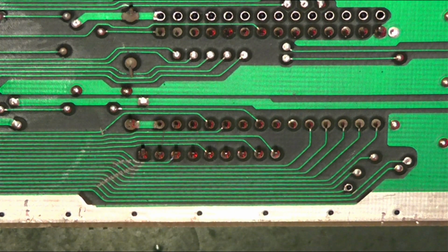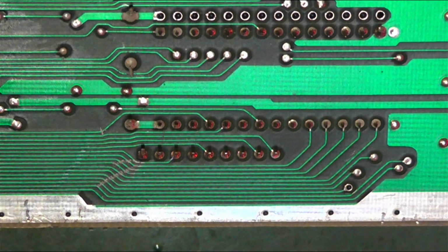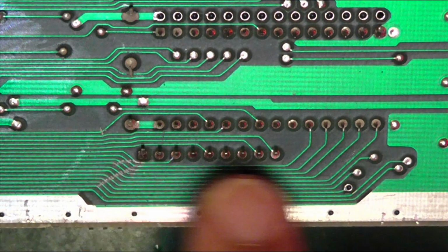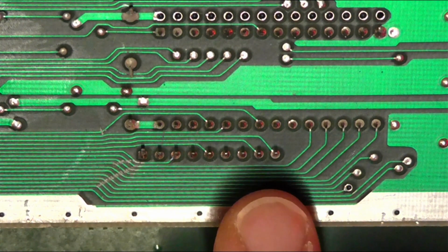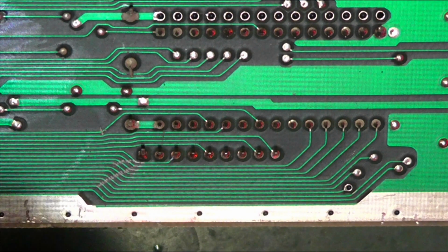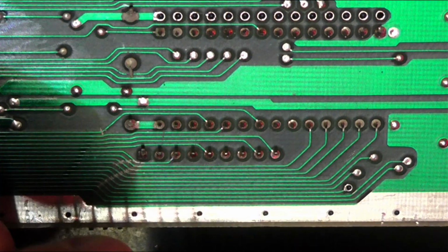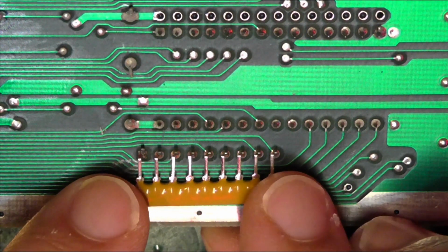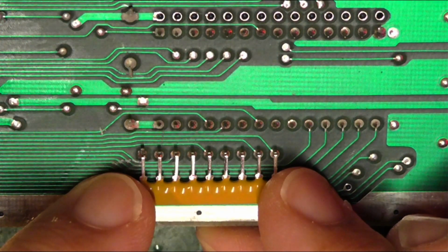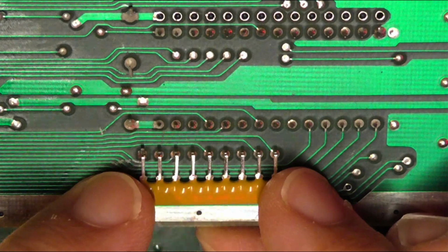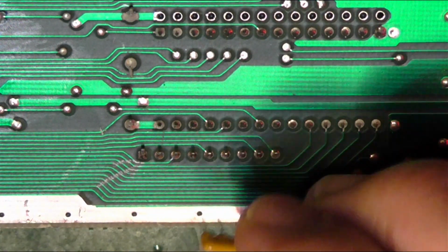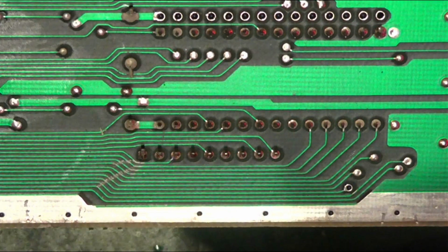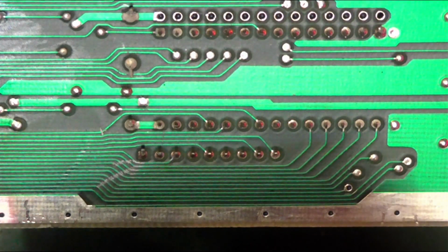Okay, so we're going to start on this one down here, which is resistor pack 4. It's probably the easiest one to work with. Just try not to damage any of these traces. What I'm going to do is try and solder this on. It's actually going to be that way around. We'll try and solder it on something like that and lay it flat, and hopefully that will work. I'll probably just do one and then flip it over and try it again in the shield to make sure it doesn't stand off too far.